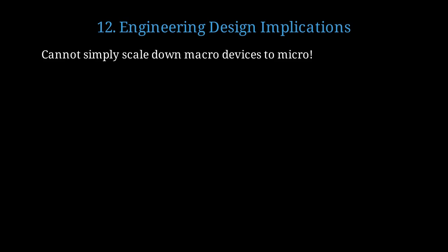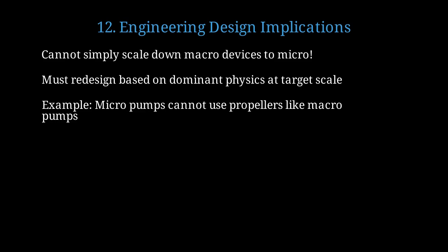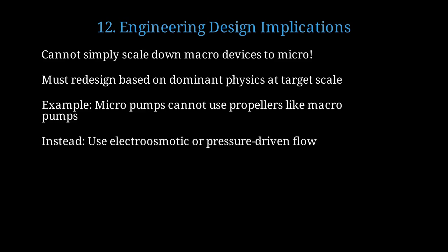These scaling laws have profound implications for engineering design at different scales. You cannot simply scale down macro-scale devices to microscale and expect them to work the same way. Instead, you must completely redesign based on which physical phenomena dominate at your target scale. For example, micropumps cannot use rotating propellers like macropumps do, because viscosity dominates over inertia. Instead, microfluidic pumps use electroosmotic flow or carefully controlled pressure gradients.